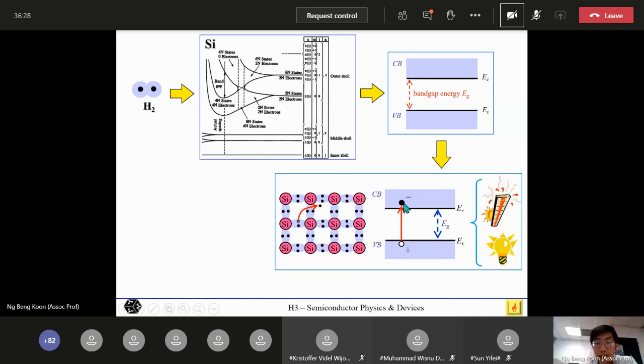In the case of the band diagram, one thing that you should also take note of is that the energy band diagram is a plot of energy of electrons. The vertical axis actually is the energy of electrons. In other words, if you go vertical, the vertical shows increasing energy of electrons. In the case of holes, because it's positively charged, the increasing energy for holes is actually downwards. So to a hole, if you go downwards, it's actually increasing in energy. So it's opposite, because the charge is different.